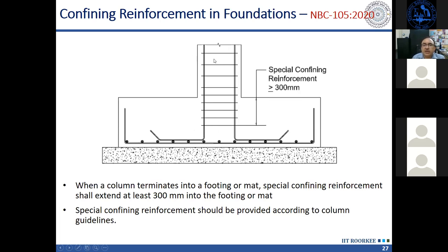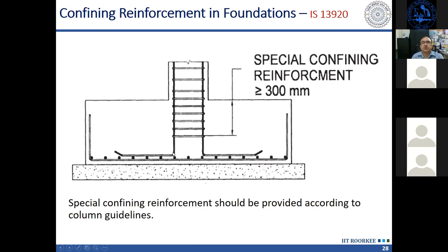And all our buildings, we will see later, we will design in such a way that the beam yields first, then the column yields at the foundation. So the foundation is also a potential location where the plastic hinge will take place, and we have to carefully detail the column reinforcement inside the foundation. Identical figure is given in